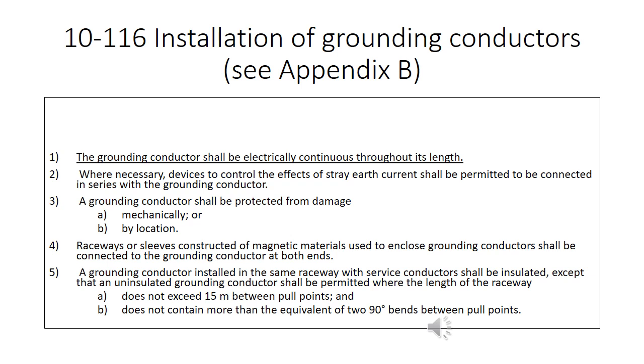So what does that now mean? The grounding conductor is no longer required to be one continuous unbroken run that is free of splices. You no longer require bus bars, thermite-welded joints, and compression connectors, splicing, and as a matter of fact, split bolts are now considered acceptable.